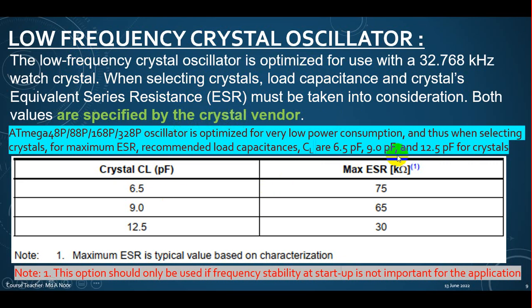Now, this superscript 1, what does it tell? This option, okay: maximum ESR is a typical value based on characterization. This option should only be used if frequency stability at startup is not important for the application.